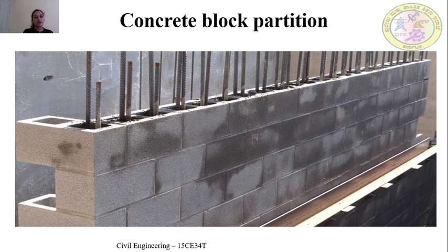So coming to the comparison of concrete blocks, cement concrete block partition has the following advantages over brick partition walls. Since the blocks are generally cast quite large in size, the number of joints in the work is considerably reduced, and even less skilled labor can work as blocks are uniform in size and shape, and hollow concrete blocks afford good insulation against heat, cold, sound and dampness.